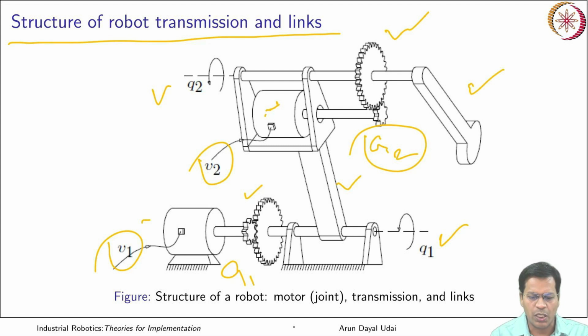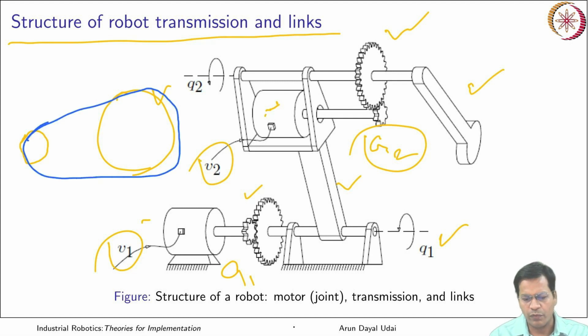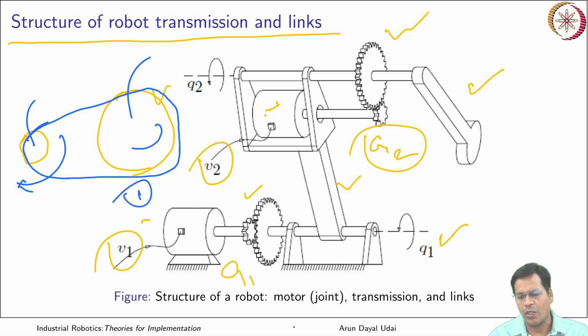It may be due to the size of the two driving and driven pulleys, and you have a belt that goes here. So even this is a reduction. This is the driving pulley, this is the driven one. So if this rotates by 2 revolutions, this will rotate, let us say, just by 1 revolution. Got it? So this is also a reduction.